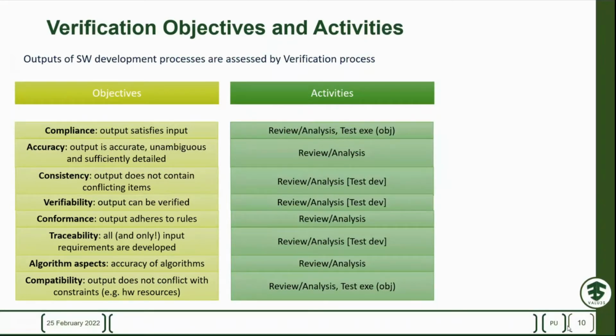So from a software perspective and the verification objectives that we would like to hit, there is a series of objectives that are mentioned inside the DO-178C, and those objectives span a series of defined objectives. So compliance, the accuracy that we would like to get, consistency and verifiability, conformance to specific rules, more importantly the rules coming from the ARP 4754.